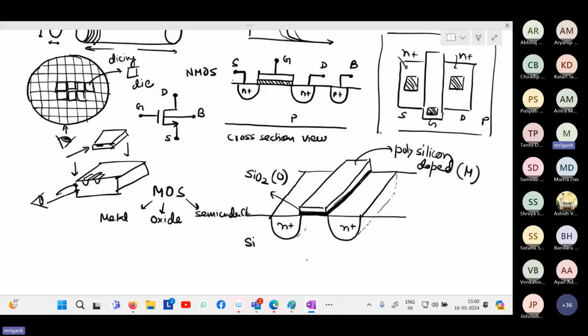So of course, the substrate is going to be thick, right? Because the substrate thickness depends upon this thickness. And ultimately, that depends upon the wafer thickness in the direction perpendicular to the plane. So silicon is supposed to be sufficiently thick. This can be several micrometers, several tens of micrometers to 100 micrometers. So that substrate is thick. And on the top of the substrate, you are creating this MOSFET.